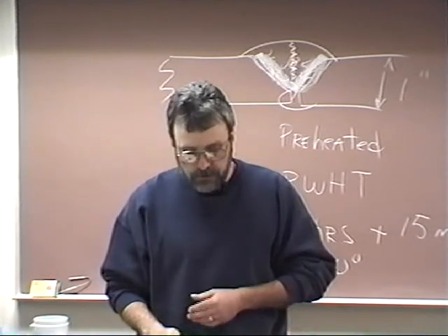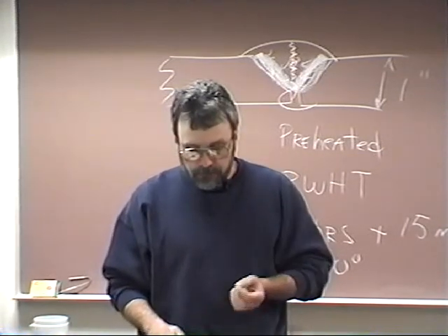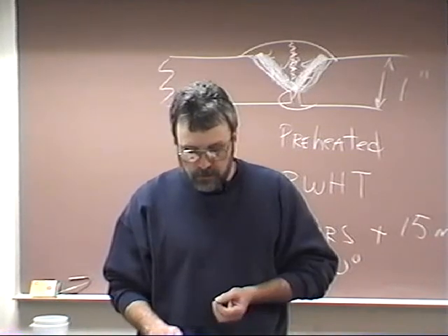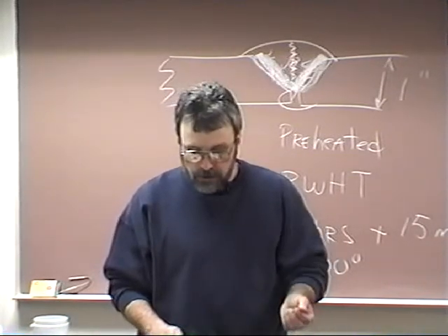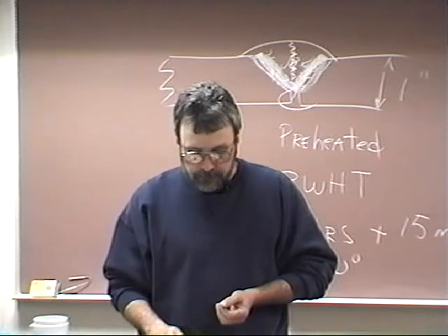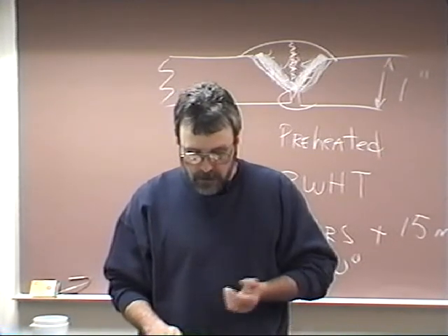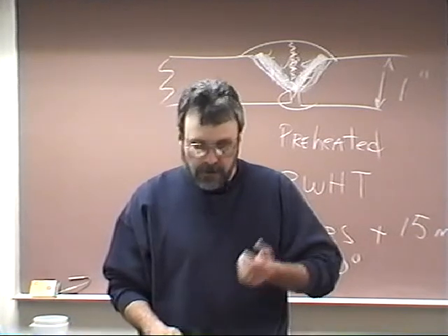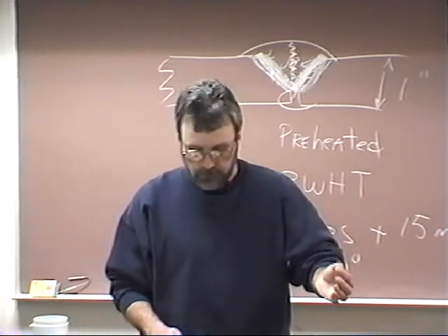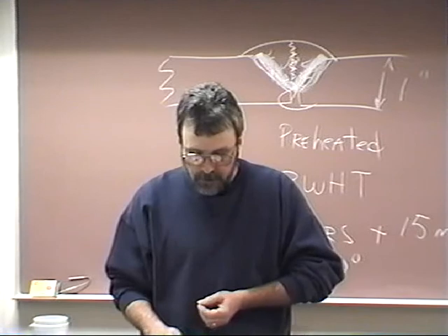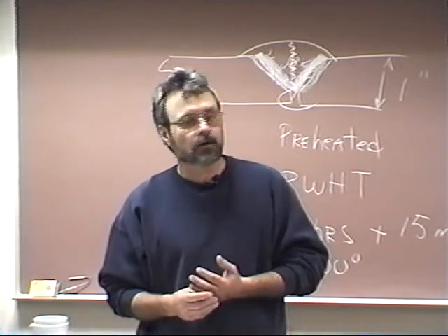Well, if you turn the page to 218, it says you're going to discern some method for exploring the defect. Determine how you're going to remove the defect. Determine if there's got to be any post-weld heat treatment, what type of electrode you're going to use. You've got to make sure you use qualified welders. And if you're using an X-ray, you may do an overlay.